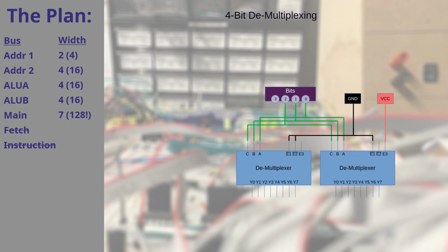The 4-bit demultiplexers are relatively easily handled with the 138 series by tying 2 of them together and using that most significant bit as the enable. Each 138 has 2 active low enables and 1 active high enable. That makes it very easy to tie those together.